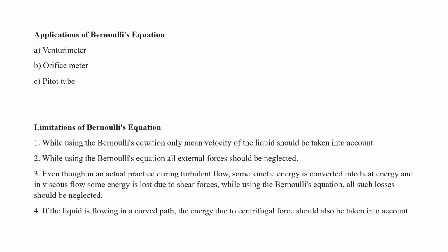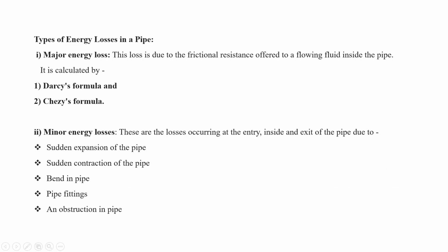In actual practice during turbulent flow, some kinetic energy is converted into heat energy, and in viscous flow, some energy is lost due to shear forces. But in Bernoulli's equation, all such losses are neglected. And if the fluid is flowing in a curved path, the energy due to centrifugal force is not considered while deriving Bernoulli's equation. So these are some of the limitations of Bernoulli's equation.